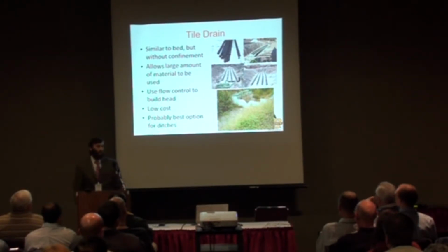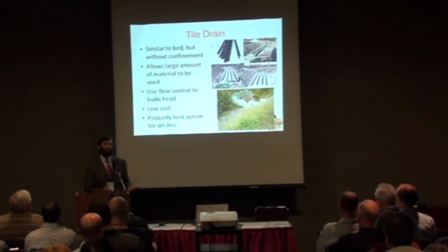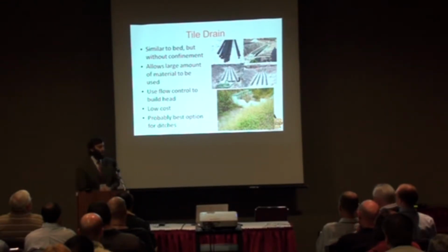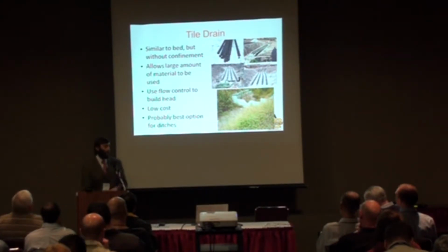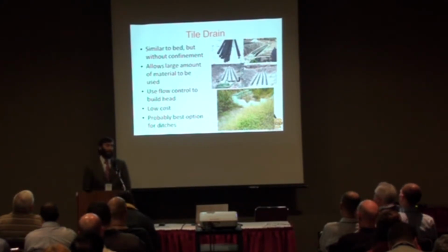So we've built many structures directly in these ditches by essentially laying tile drains, backfilling them in the ditch with some of the sorption media, often using flow control structures to control the hydraulic head in order to build enough head for water to flow through it. These are pretty low cost and probably the best option for ditches. Works very good for ditches.